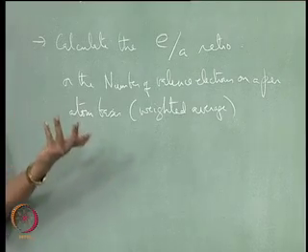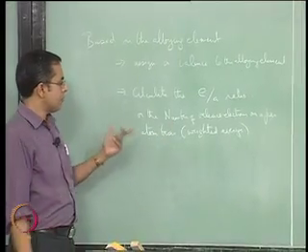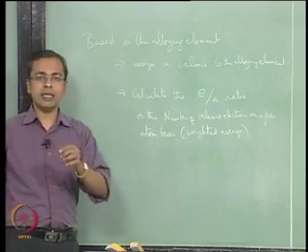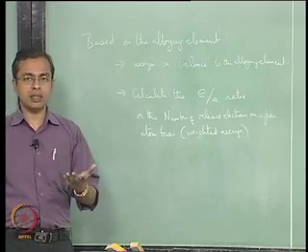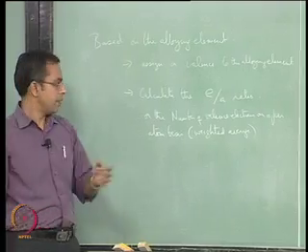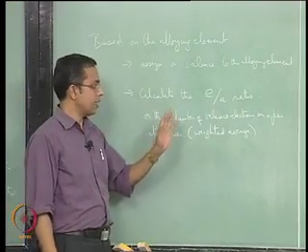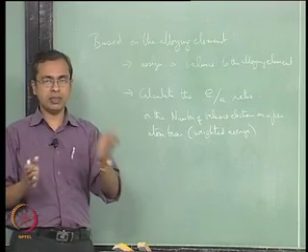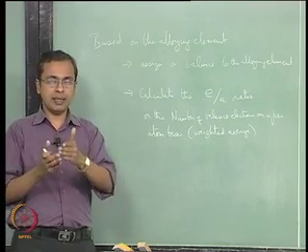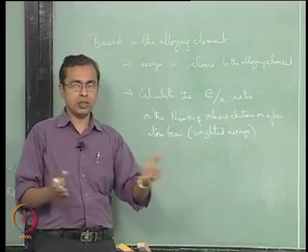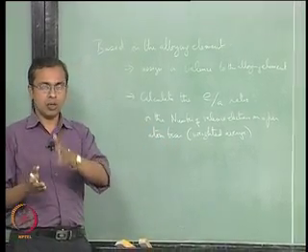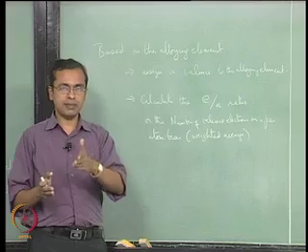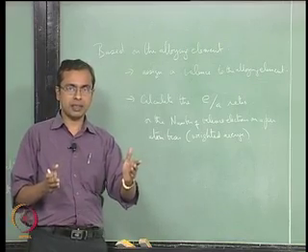This is where the situation becomes interesting, because we find that regardless of the alloying element that you are using, the composition at which that change occurs from FCC to BCC is varying from system to system. So depending on the alloying element that you use, the composition at which that change occurs from FCC to BCC can be a different composition, right.